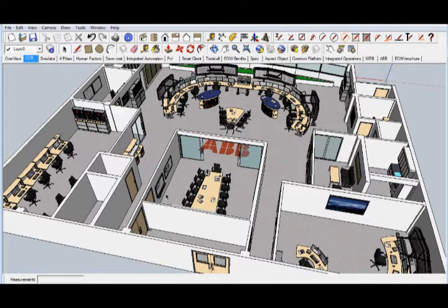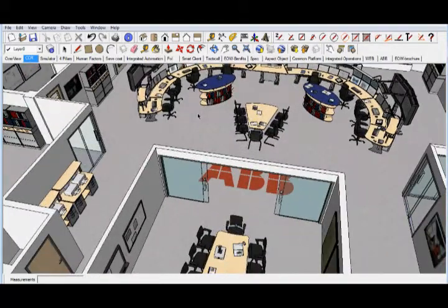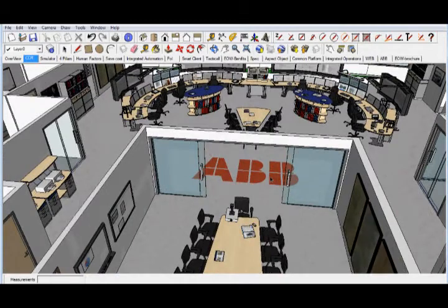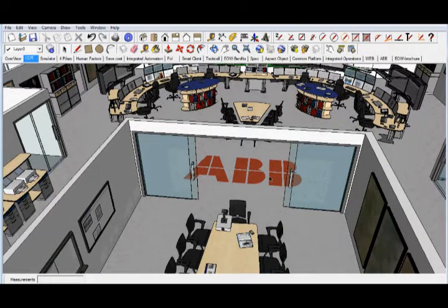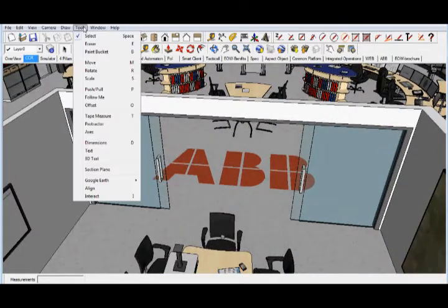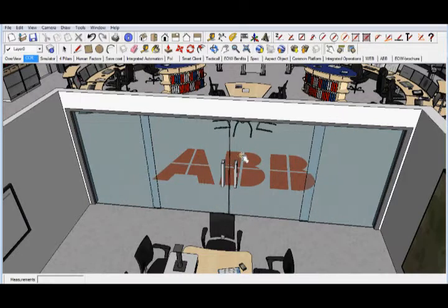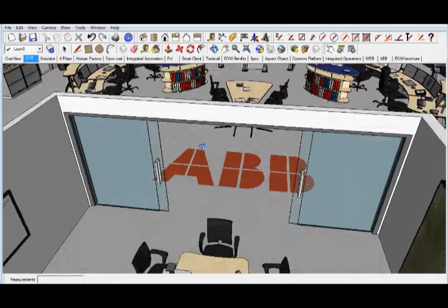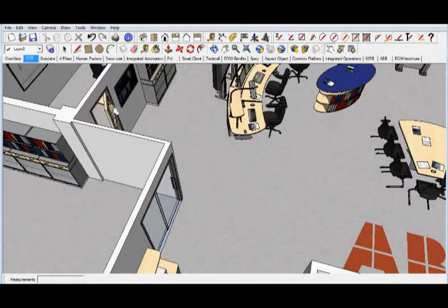I think also in the future I will provide ABB with a lot more tutorial videos on how to create walls, how to create doors and things like that. And actually we have built up a lot of good functions which make it very easy to attach doors and windows into walls. For example, we have some different kinds of tools, and one tool is interact. It's a short command, I, and then you can just click on the windows and it goes up and down, and that's applicable for all the doors we have. It is very easy to close them and change them.